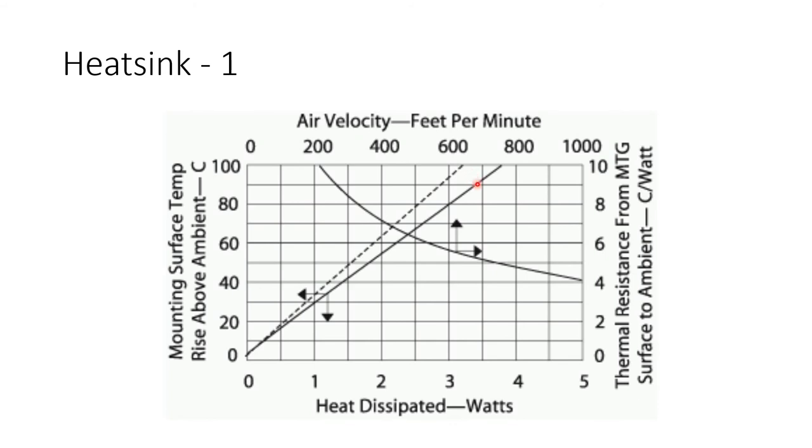The second part of the graph gives the air velocity versus thermal resistance, but we don't know the air velocity, and because we are not applying any airflow in our system for now, because we are using natural cooling most of the time. If you are using forced cooling or airflow to cool our power electronic device, then you can use the second part of the graph.